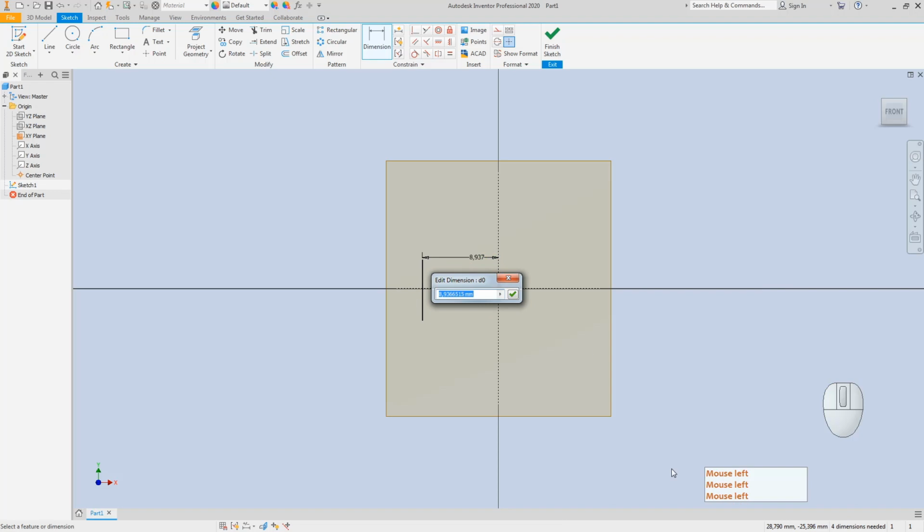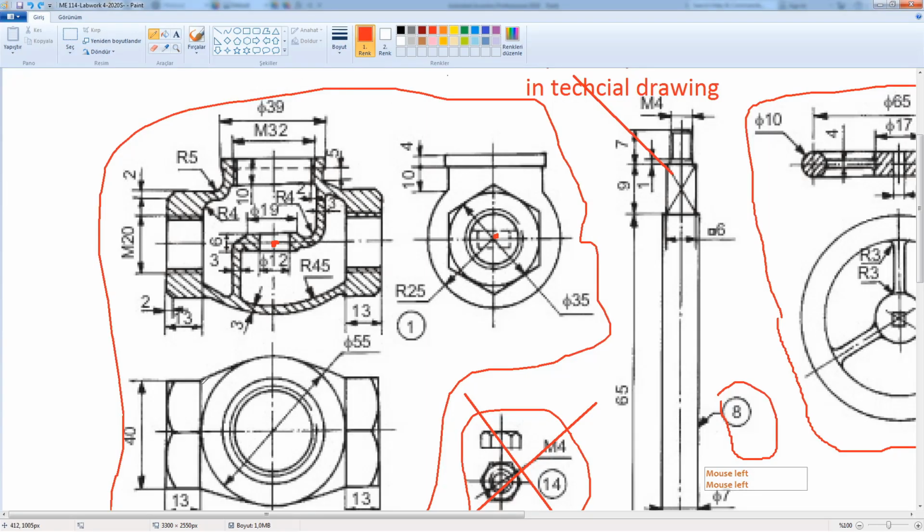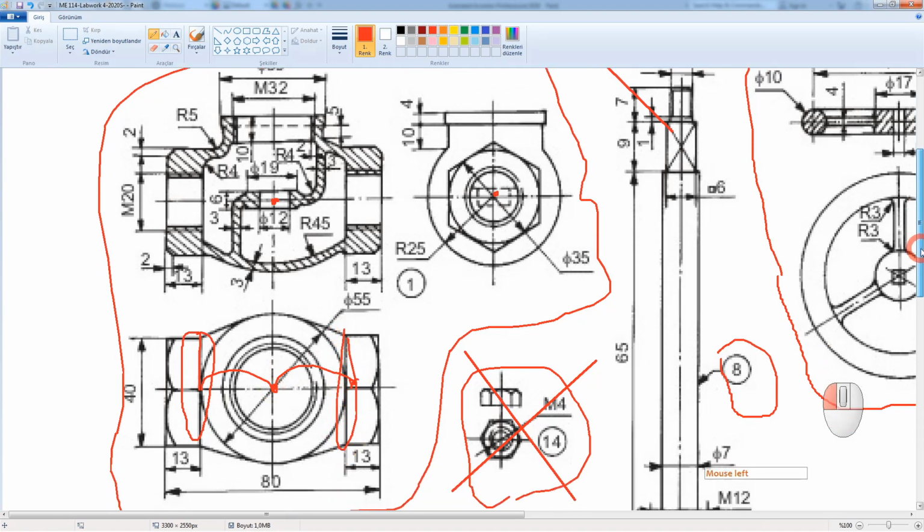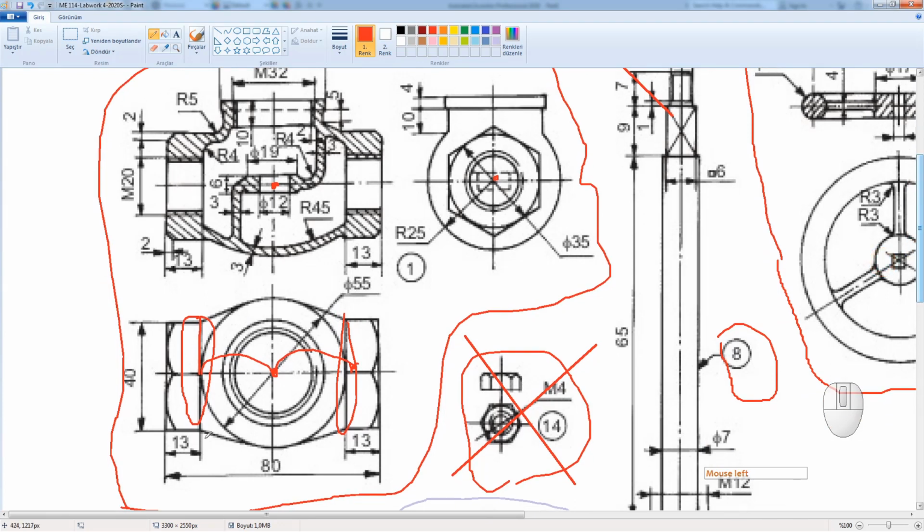The first thing that I'm going to do is make this dimension 40 mm. I created this point. I'm going to sketch on that point, and it is about 27 millimeters far from the origin point. I will just create 2 planes on this sketch.